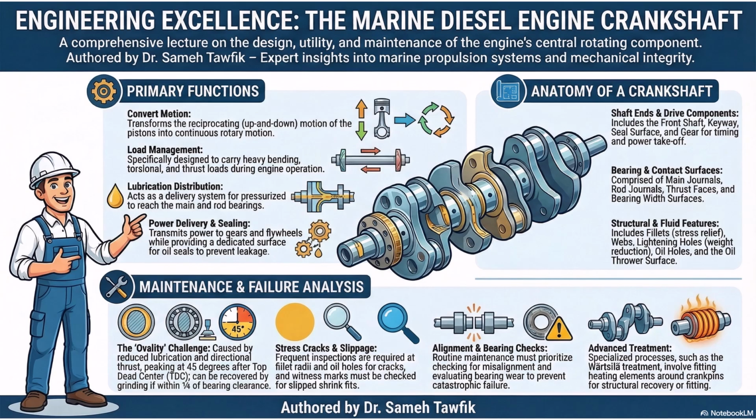Exactly. To assemble or disassemble a component with a shrink fit at that scale, or to relieve the immense internal stresses within the forged steel, you have to precisely manipulate the temperature of the metal. The technician is manually applying specific thermal treatments to expand the crank pin, either to mate it to a web or to alter its metallurgical grain structure.